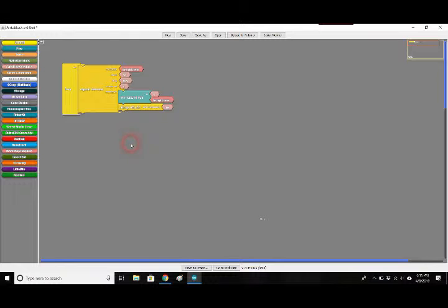Okay, so here's our next piece of code. This should allow us to get our LED, I only have one here just for starters, on pin 3 to slowly, gradually brighten. So it goes from dim to a little bit brighter, to a little bit brighter, to a little bit brighter until it reaches its max brightness, and then it starts over from being dim again. This is opposed to just turning off and turning on. We have a lot more modes here because we're using this set analog pin block.